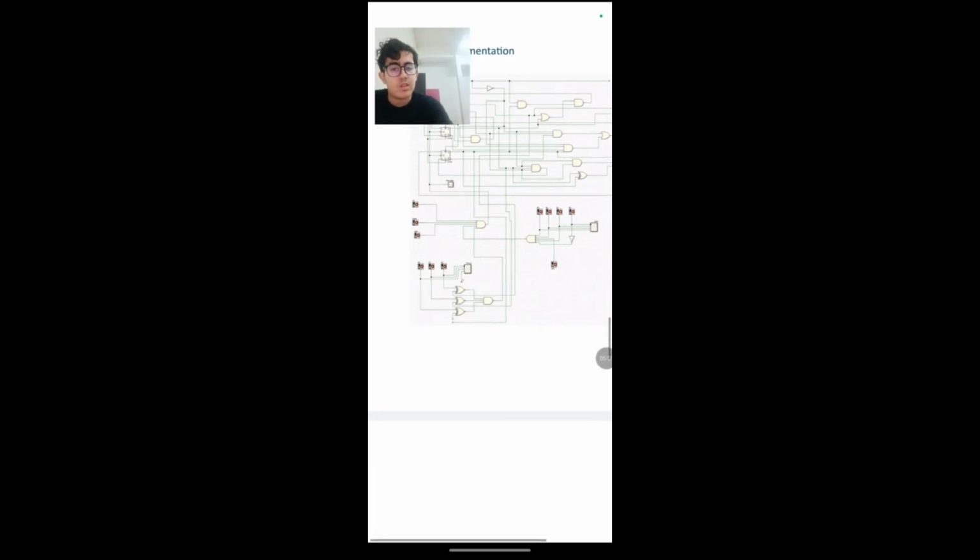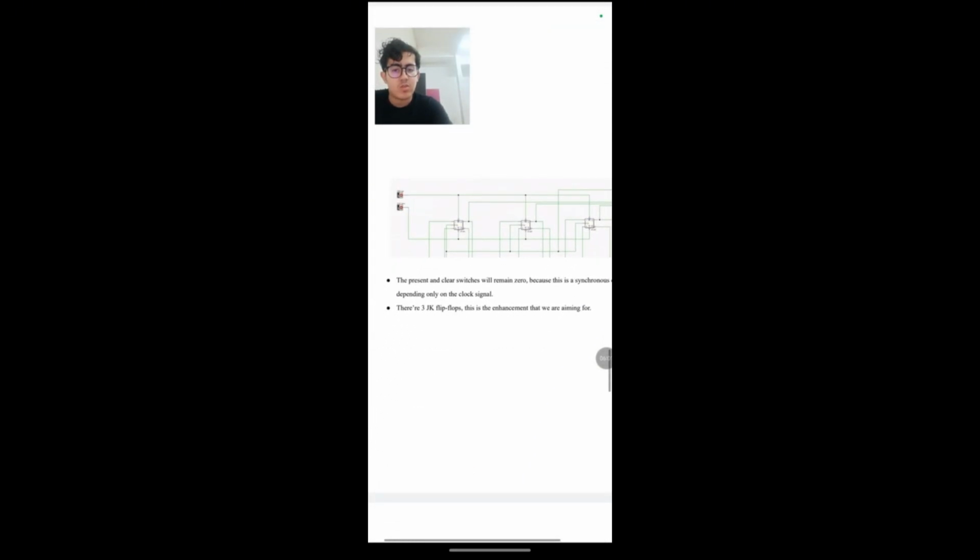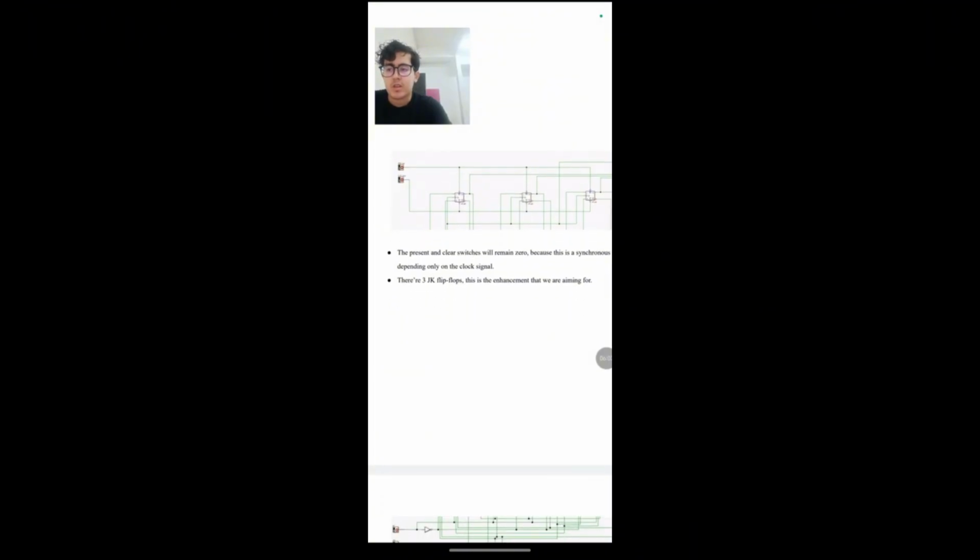Another one I want to cover here is the detail of the security and stop logic and the green light condition. For this one, the input management and safety features of the elevator: to move, it must satisfy the safety green light condition, which is handled by a strict clock gating mechanism using the AND gate.